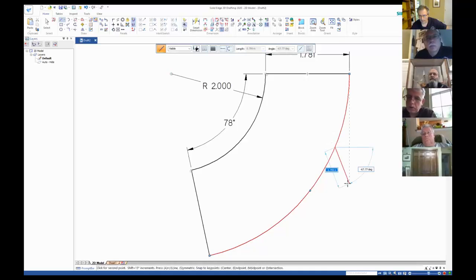Hey, Greg, is this tool smart enough to let you know if, let's say, a part that you're designing is fully dimensioned? I don't know, but if you start changing dimensions and see odd behavior, that will tell you if something's missing. In our parlance at work, we call it under constrained or over constrained. I don't know if it'll tell you. That would be pretty difficult. But when you start changing dimensions and something goes awry, you'll know that it's under constrained. Or if you try and change a dimension and it doesn't move like you expect it to, it's over constrained.